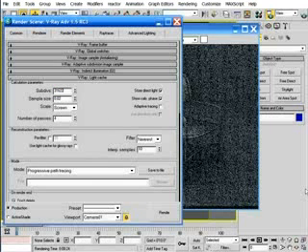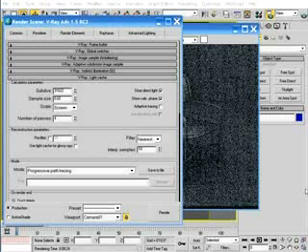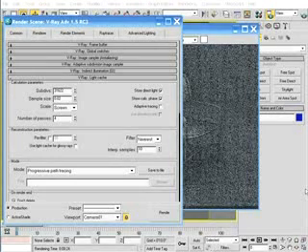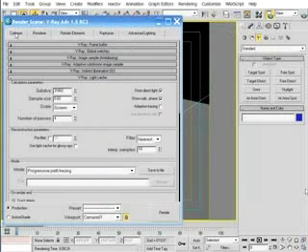Now, since the subdivision value represents the square root of the number of rays traced, doubling the rendering size means that you're going to need to quadruple your subdivision value to get the exact same rendering quality. This in turn quadruples your rendering time, almost exactly, in fact.